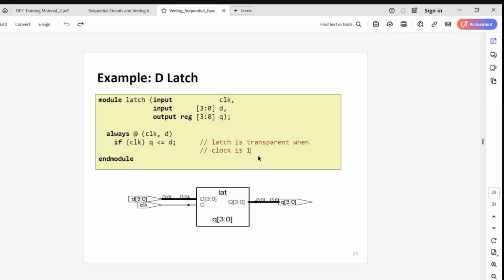The latch is level sensitive. We have two levels, high and low. High is 1, low is 0. In one full cycle, you have one high and one low. If there is a data change within the first half cycle, the data can change again in the second half cycle. The data will not be stable throughout the clock pulse. That is the problem with the latch, so don't use a latch to store data.